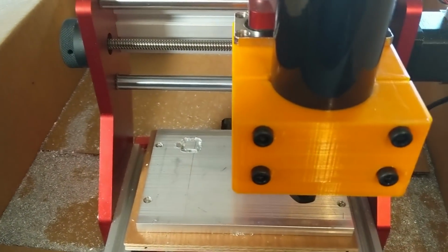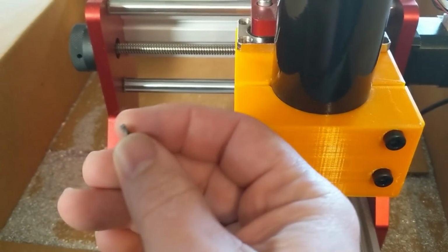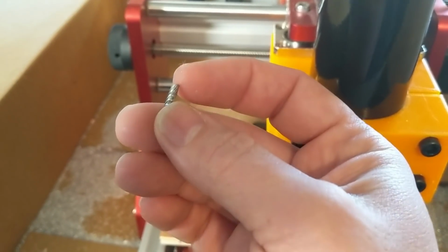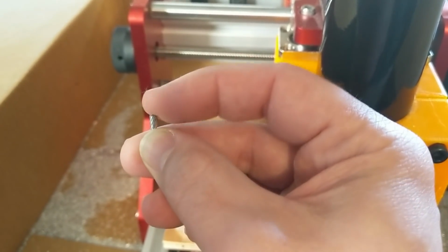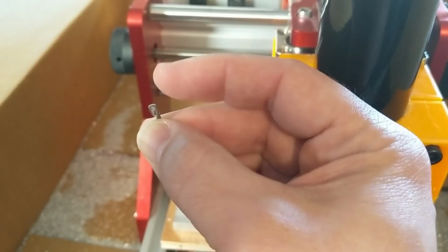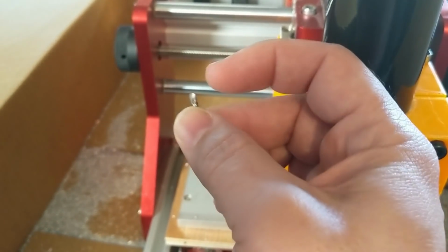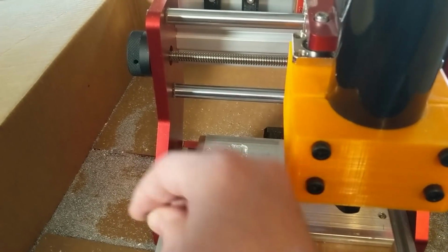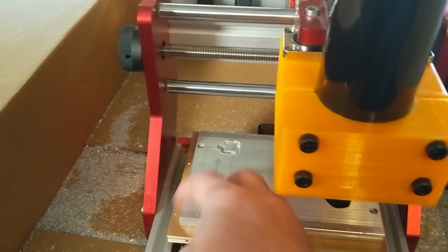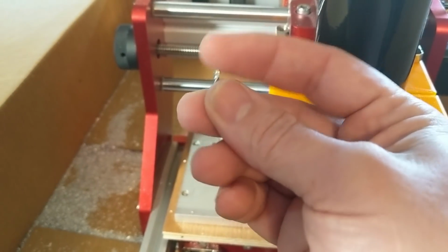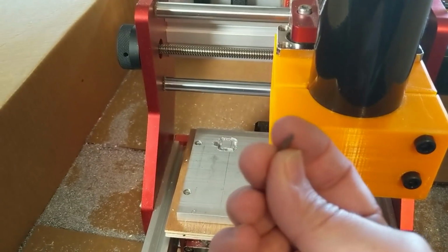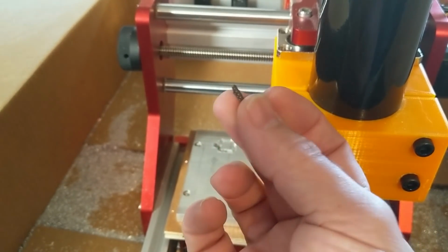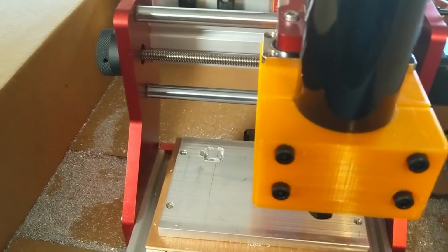So really bad. That chatter causes the bits to break. Actually, this is the first bit that I've broken, but first it broke the tip off of the cutter, the business end right there, the most important part of the whole cutter, just basically chipped off. And that's just because of the vibrations, the chatter in there. And once that was no longer able to cut, the machine was trying to push it through the material that it wasn't cutting, and it just snapped that off. So there's my first 1/8 inch single flute end mill bit that I've broken.